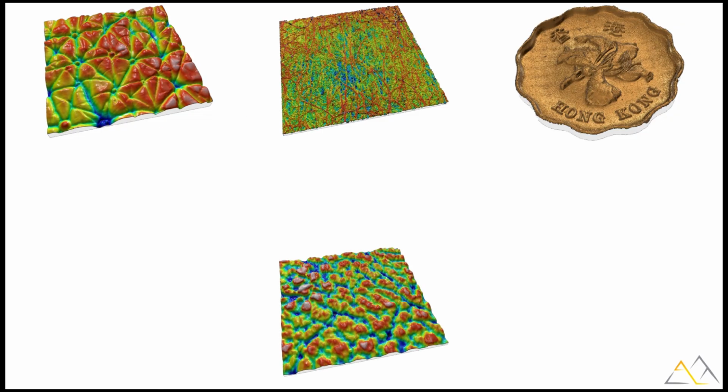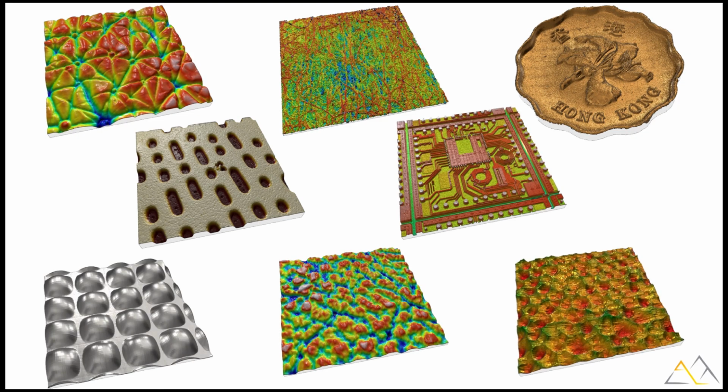Outside traditional machining, many modern surfaces are not simple or homogeneous. Some are textured or structured to achieve a specific function, such as improving adhesion, reducing friction, or enhancing hydrophobic behavior. In such cases, the choice between a profile or an areal measurement is directly derived from the surface complexity.